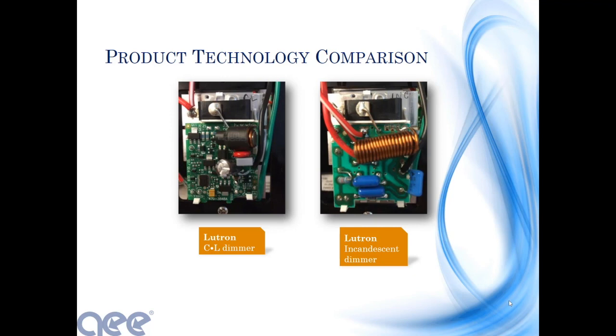So it really comes into play when you say, I've got a dimmer on the wall doing my incandescents in my conference room, I'm good to go, I'll just take those incandescents out and put in LEDs. And then you wonder why you get flicker and why you get overheating in the dimmer, why you potentially pop circuits and things like that. This is what this affects.